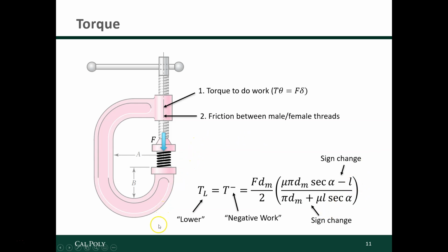In order to solve problems that are involving torques and forces in power screws, these are the equations to use. For their source, you can take a look at the derivations in the other videos I provided. It basically boils down to thinking of the screw threads as a ramp, and so you just unwind the helix, and the analysis is surprisingly straightforward for maybe as complicated as the equation looks.